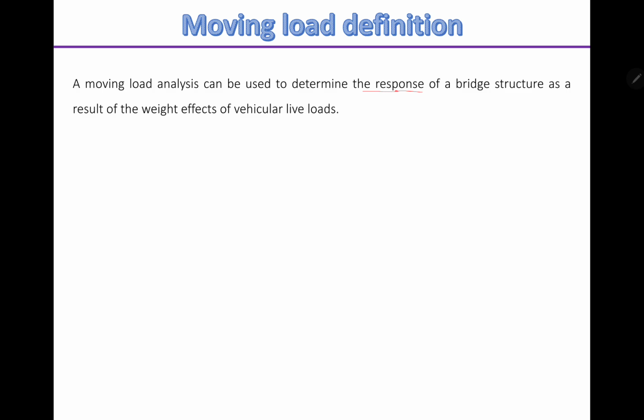The particularity of these moving loads is that their position changes along the superstructure, so their effect can also change, and we seek the maximum and the minimum of the response of a bridge under these moving loads. In fact, the CSI Bridge software lets us get different results, either the maximum or the minimum of different effects.